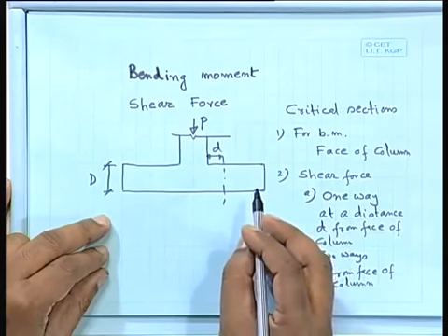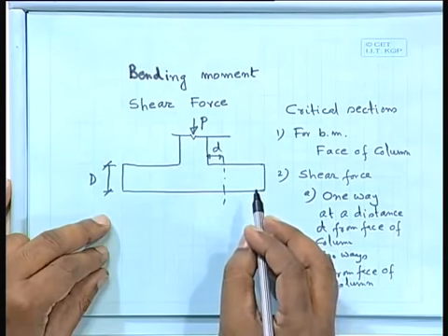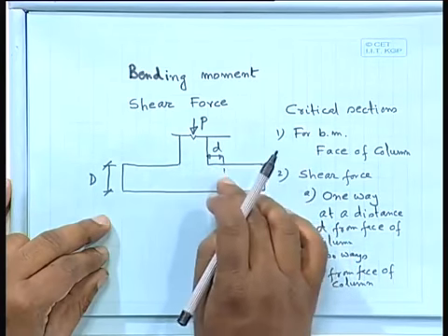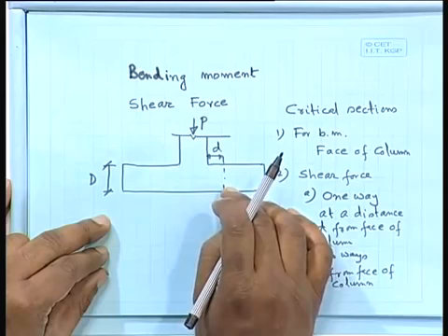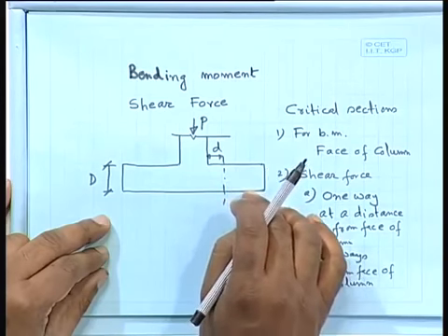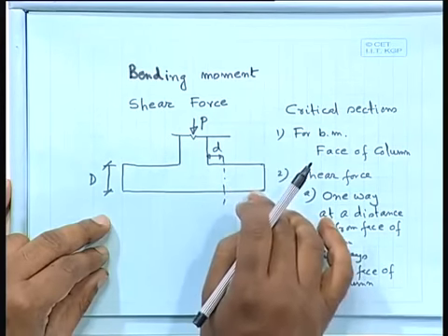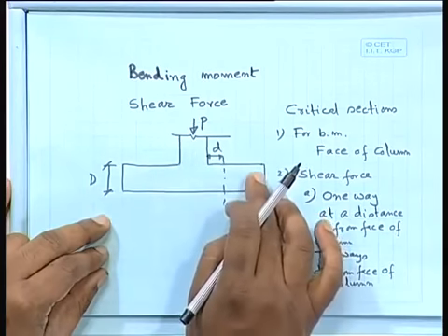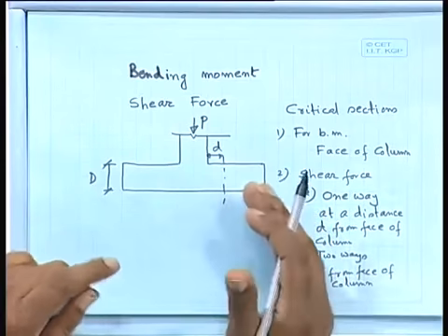Then we have to provide reinforcement. For this type of thing, you can consider this as a slab. You are not providing any shear reinforcement, no stirrup. So here the critical stress, tau c, should be less than 0.35. You should consider that, because if it is more, then you have to provide shear reinforcement.